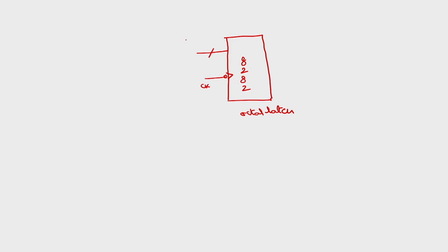In total in the 8086, 20 lines have to be demultiplexed. 20 lines are multiplexed in the 8086, out of which 16 address lines are multiplexed with data and 4 address lines are multiplexed with status. This is AD15 to AD0. Here there are two 8282 chips, but I am showing only a single one, and I will show this as 16 lines.